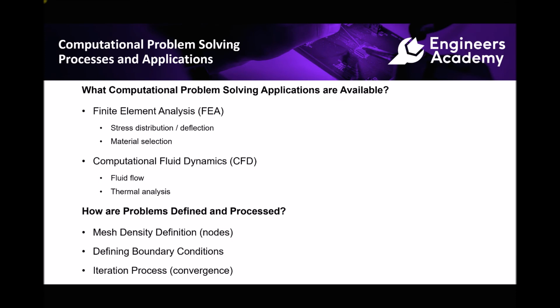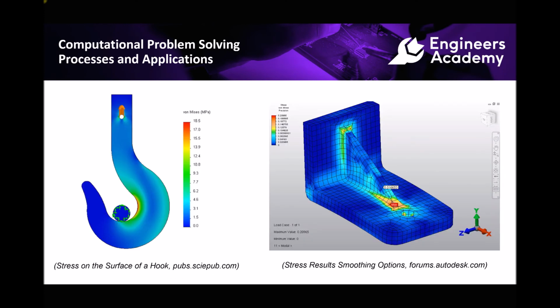Now the final thing that I want to mention is the iteration process. I mentioned earlier in this video, referring to our diagram on the right hand side, that the software carries out a calculation at every single one of these nodal points based on the boundary conditions that we apply. So the only things that this software knows is that a force is being applied at this hole and the back of this bracket is fixed or inset in some way.